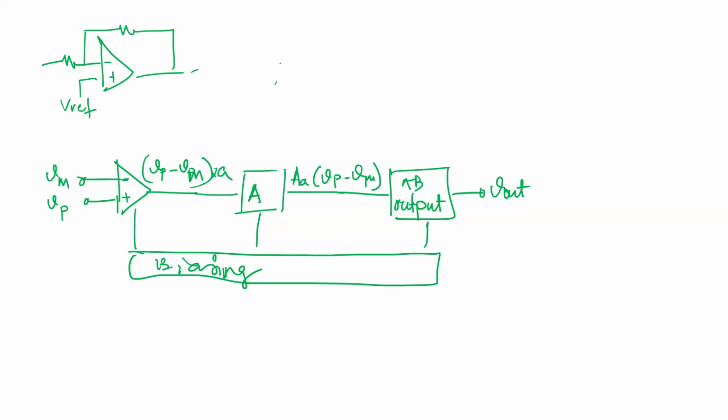So, there are a few definitions we'll just use. Obviously for this configuration you need a differential input, but one of the main reasons we need a differential input is also to do with noise isolation. Okay, so typically the differential input Vd is expressed as Vp minus Vm. So that's the difference in these two voltages over here.